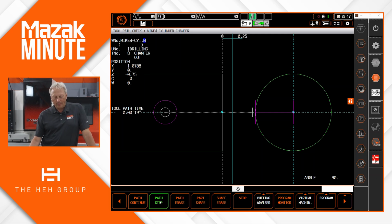As I hit step, you can see it moved over. And again, I like the 2 view because I get a top view of it, and I can see that my C-axis rotated. And if I look at my position screen over here, you can see I'm at that 14.7 degrees. Now as I hit path step, you're going to see it plunges down. And it will automatically calculate out the depth based on those interferences and what the depth of the pre-drill was. Now when I go ahead and hit step again, it's going to give me a 360 cut.